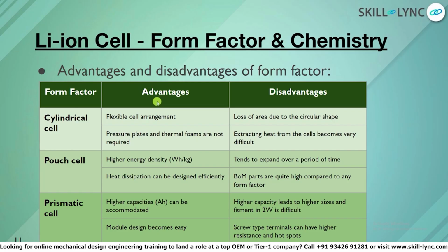Another advantage is that cylindrical cells have a cylindrical can, made of nickel or SS, anything. And if you go into a little bit of basics of mechanical engineering, you could identify that a cylindrical shell will have a higher hoop stress resistance against internal stresses.